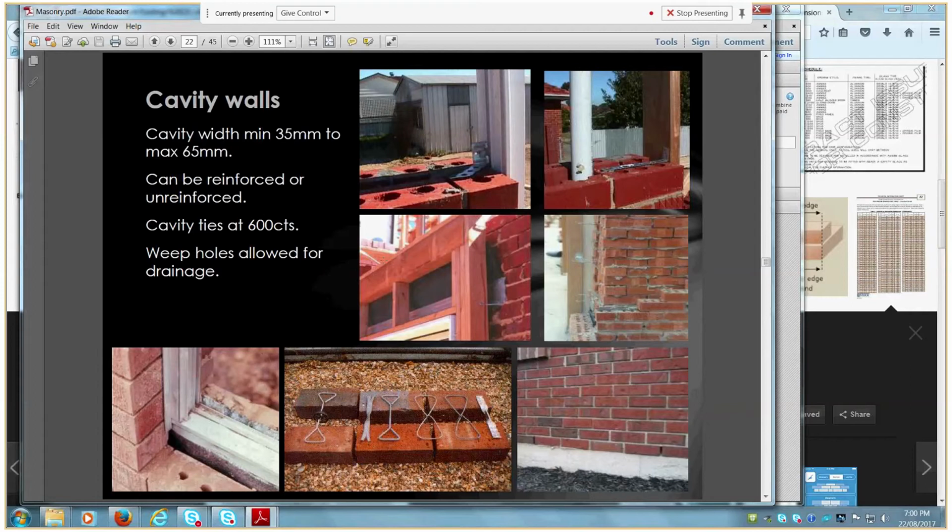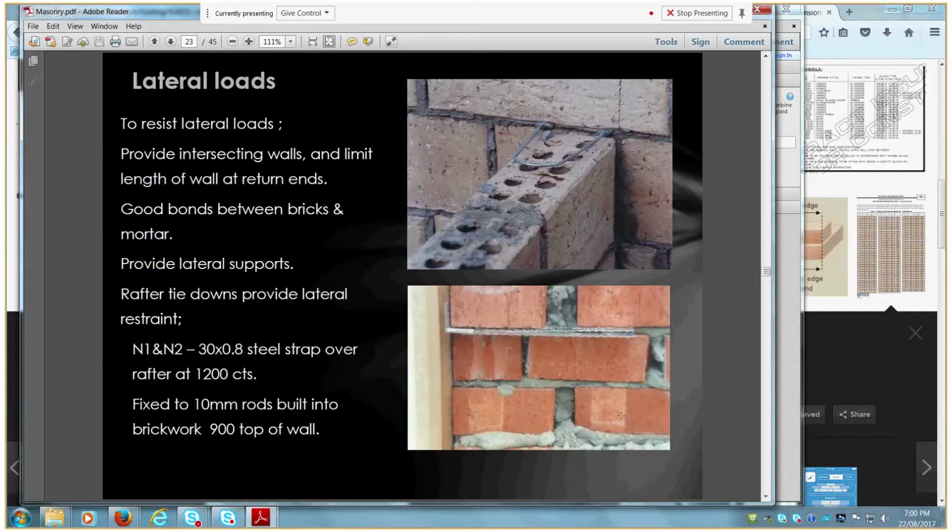The way you think about moisture with masonry walls or typically brick walls is that yes, you try to stop moisture getting into the wall. But basically, it should always be constructed in a way that gets water out, because you can fairly much guarantee that there will be small amounts of water that make their way into the walling somehow. And it's about making that water exit.